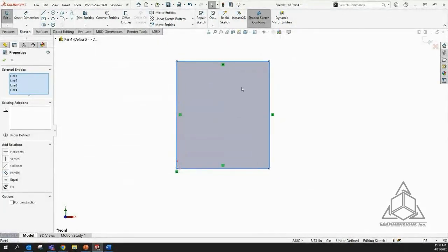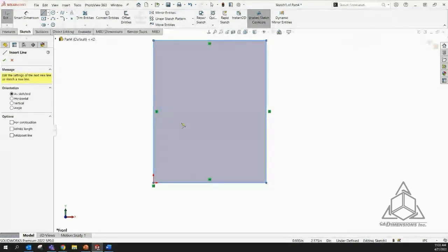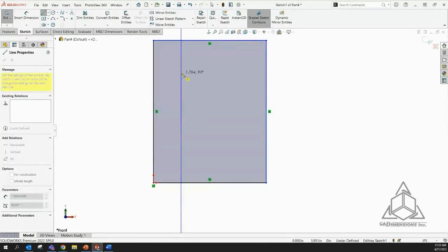So let's take another look at ways to create lines. I'm going to grab my line tool, and we just showed the click method. But if I click down and drag, maybe because I only want to create a single line, and then release, notice my cursor is no longer connected to that second endpoint. I can create a series of individual lines without creating a completely closed contour. So those are two different ways that we can do that.